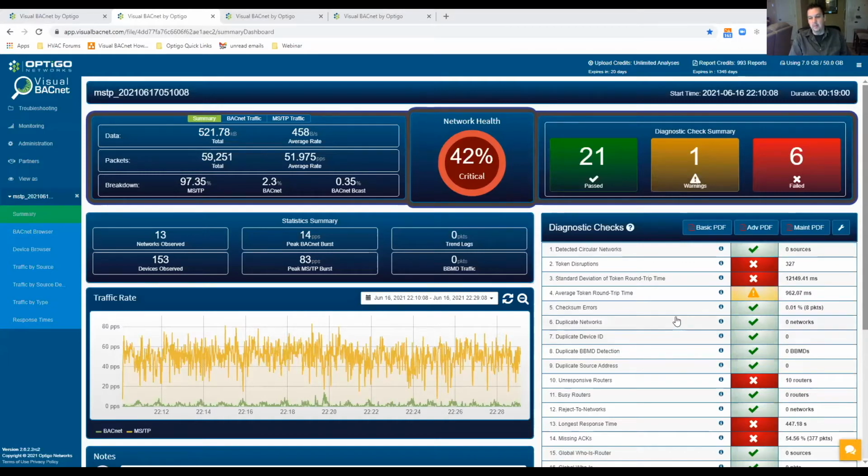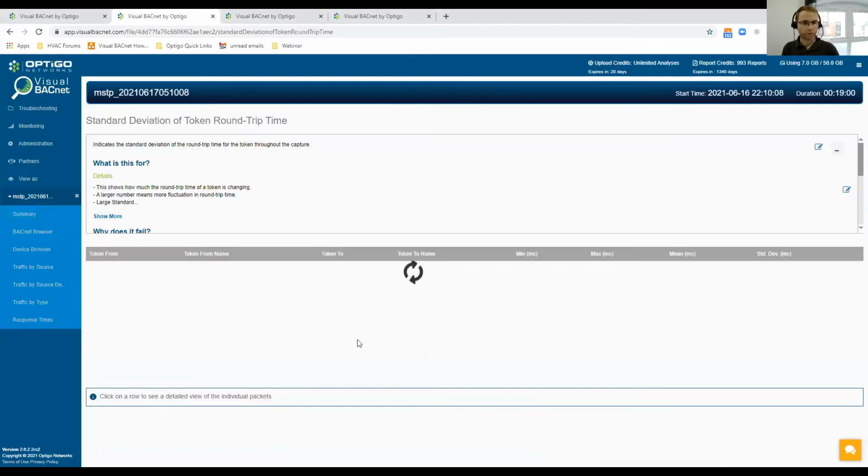Aside from breaking the network, is it a kind of a combination of breaking the network, getting another Visual BACnet, another Wireshark file, and start piecing it together at that point? So yeah, like you said, once you start seeing this data and we knew it was bad, it was a matter of breaking the network down. Fortunately for us, we had a couple of devices right next to the panel. So that was quite easy. Cut the network there. Let's get these first 2 devices online. Can we get these to communicate?